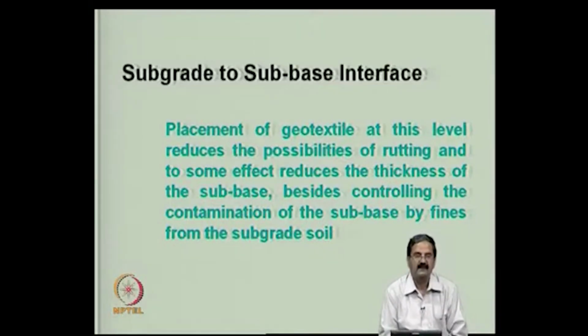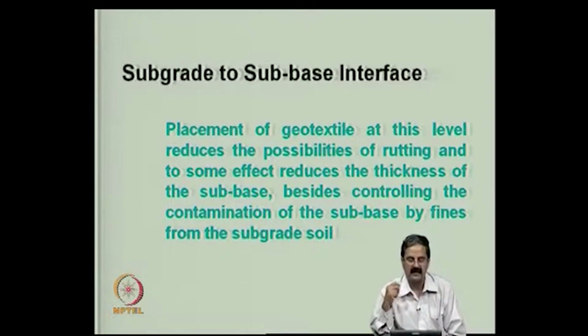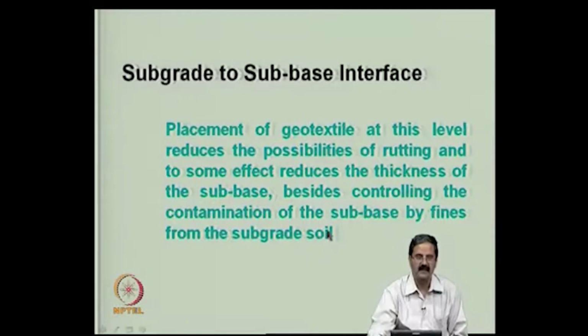What are the failure modes of flexible pavement? One is rutting. Rutting means the formation of depressions, that is called rutting. Then the fatigue. Fatigue is because of the number of load repetitions that you have, and fatigue and rutting are the two main criteria, at least if you look at pavement design for flexible pavements, bituminous pavements, right?